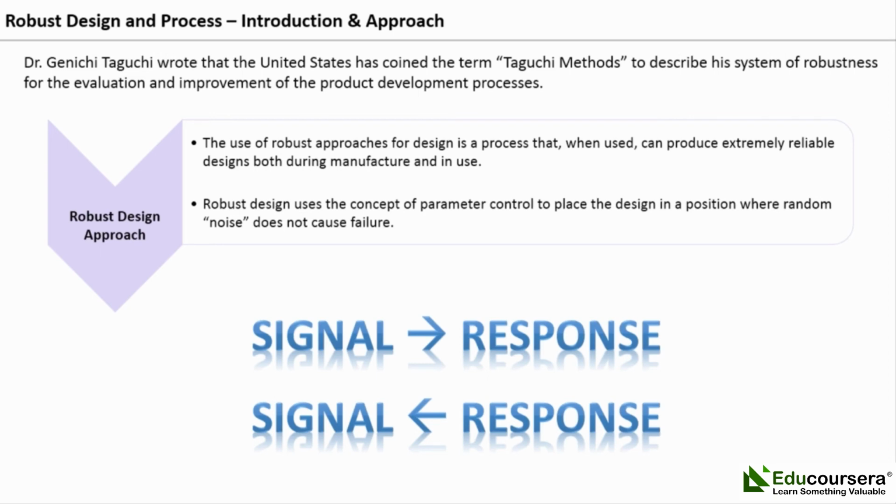Examples of noise factors in furnace design include tolerance design, outside temperature, parallax errors in dial setting. The noise factors have the ability to produce an error in the desired response. The function of the designer is to select control factors so that the impact of noise factors on the response is minimized while maximizing the response to signal factors. This adjustment of factors is best done using statistical design of experiments, or SDE.